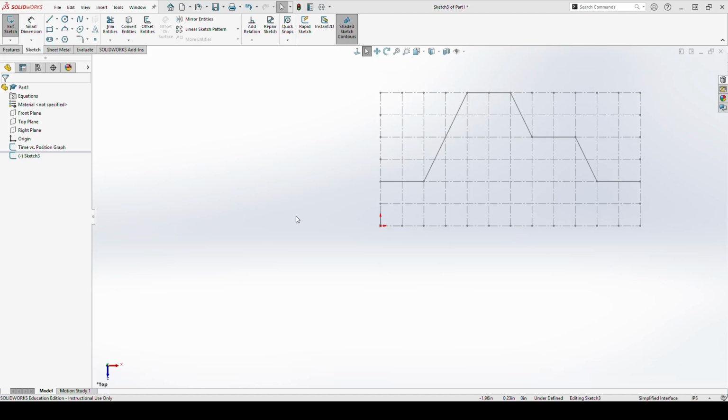The focus of this video is going to be on creating a very simplistic version of a cam using SolidWorks. However, what I really want to focus on is our fit to spline command, which we will use along this path. There are better, or at least simpler, ways to create cams depending on what you're after within SolidWorks. This works very well and is fairly simple as it is. But it's a great way to illustrate a way to create a spline without using the regular spline command.